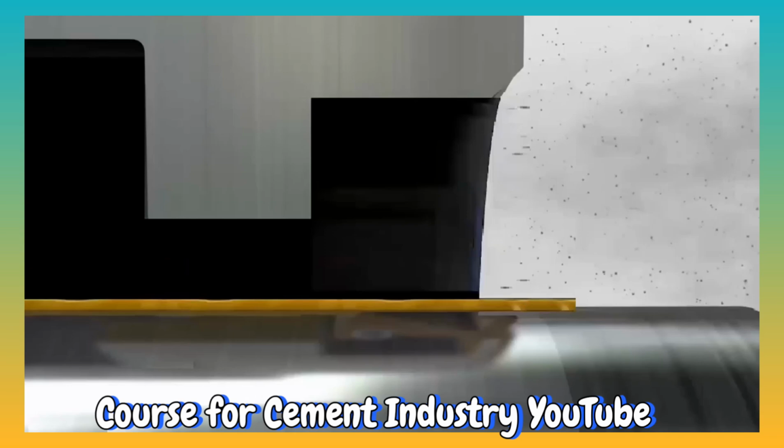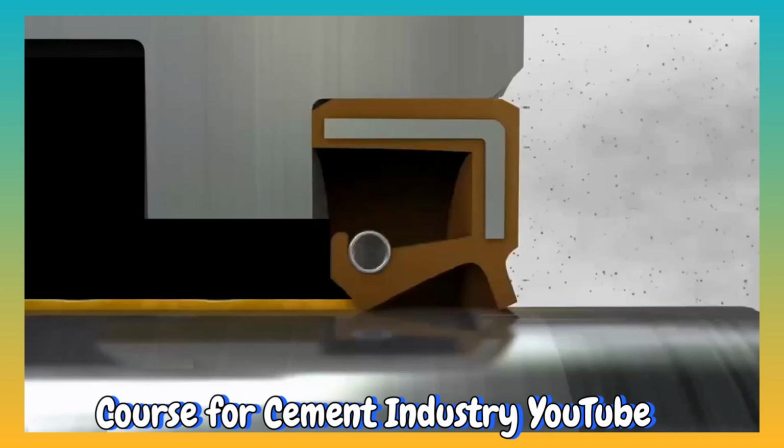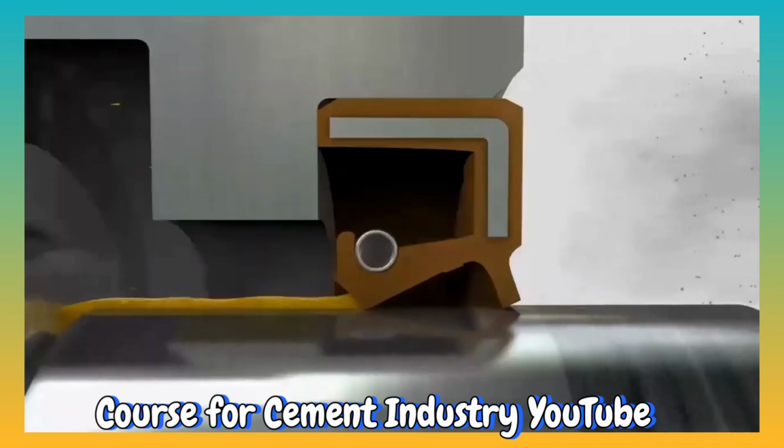If the lubricant comes out, it can cause the amount of lubricant to decrease, which causes the engine to wear out and be damaged due to lack of lubrication. The oil seal closes the gap between the shaft and the engine housing so that there is no medium in the engine housing that can easily leak out when the shaft is stationary or rotating. And your engine runs well without a lack of lubricant or leakage of working fluid.